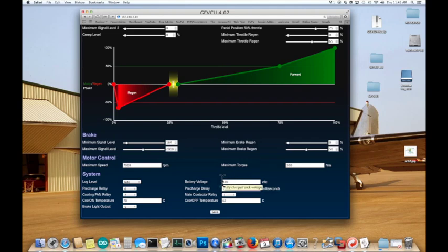Now, for the first block or so, anytime it goes above 330, we're going to reset that kilowatt hour meter. But within a block, we're going to be safely below 330. The only time it'll go above the 330 level would be during regen, and actually we don't reset the kilowatt hour meter on voltage spikes if there's any regen going on at all.